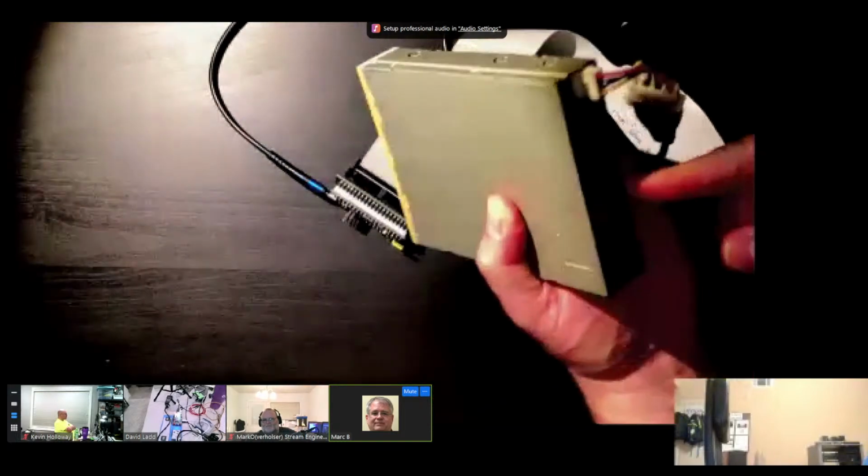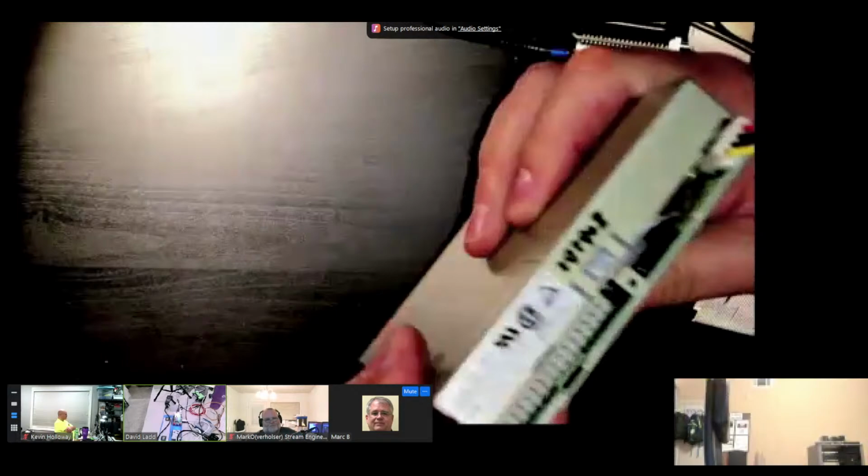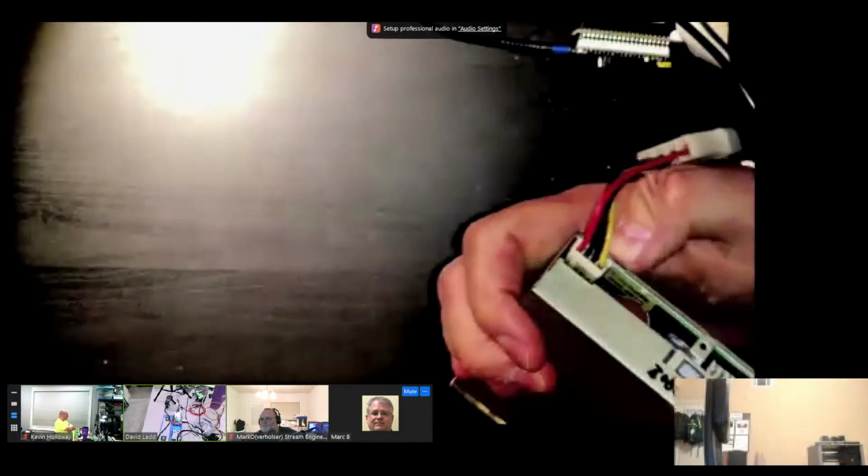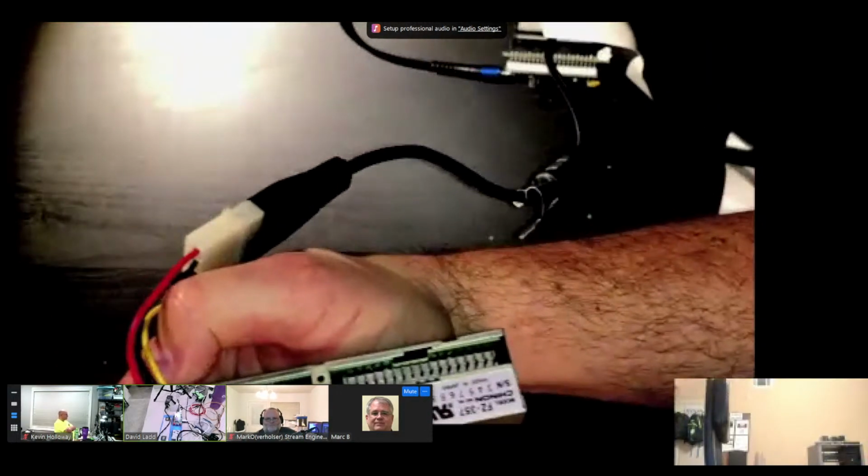It should go to the bottom, I think. Look for an arrow on one of the sides. The arrow would be pin 1. Sadly, I can't see it from here. You'll have to look for a 1 or an arrow. Or that little cutout in the frame should be the keyway.